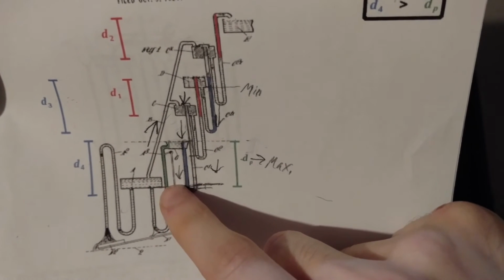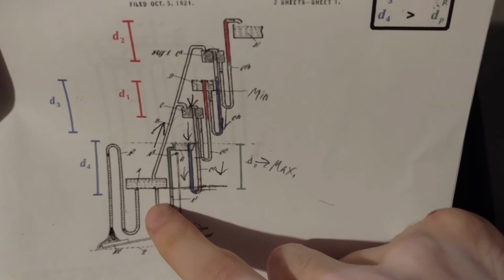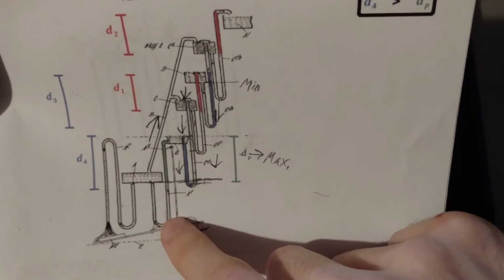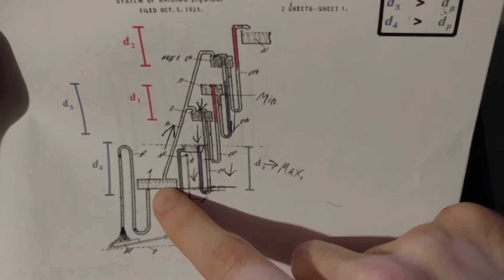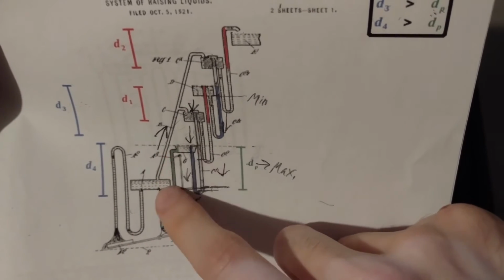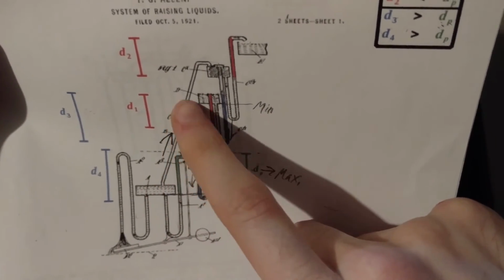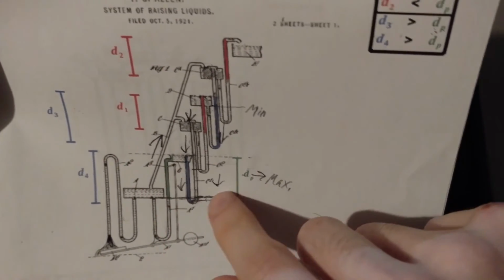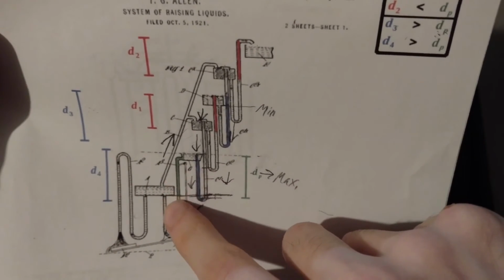I'm not stating it exactly right, but basically the pressure from the bottom of the operating tank down to that trap on this side will cancel out the pressures on this side. So the pressures you have left are determined by the bottom of this operating tank going to this water line. That distance is the only thing generating pressure, because otherwise everything below here is being nullified. So anyway, that's your D, maximum.